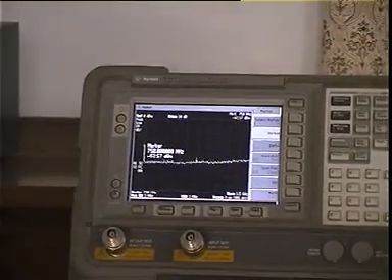Now why is logarithmic scale important? Often in communication you will find that power is represented in a logarithmic scale. The reason being that when a signal travels from a transmitter to the receiver through the communication medium or the channel, the signal can change power over a large scale. For example, let's say the transmitter transmits a few watts of power, and at the receiver I am receiving microwatts of power. When I am transmitting 1 watt of power, I am receiving 1 microwatt of power at the receiver. The power has changed by 6 orders of magnitude.